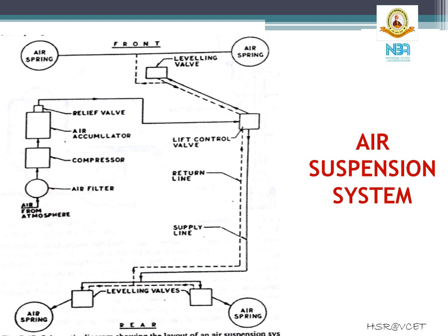There are several advantages of air suspension over conventional metal springs, such as a variable space for wheel deflection is put to optimum use by virtue of an automatic control device. Because the vehicle altitude is also constant, changes in the headlamp alignment due to varying loads are avoided. The spring rate varies much less between the laden and unladen conditions as compared to that of conventional steel springs. This reduces dynamic loading. It improves the standard of ride comfort, and the noise reduction attained with the air springs reduces both driver and passenger fatigue.